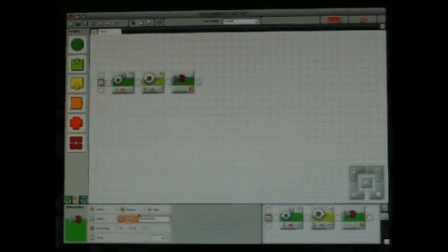Next is the record play block. This one is fun to mess around with a new robot design with. You can select the motors to record, and you can select whether to record or play. Name the set of moves. This is like a variable name that you will give to the specific rotations that you move the motors.